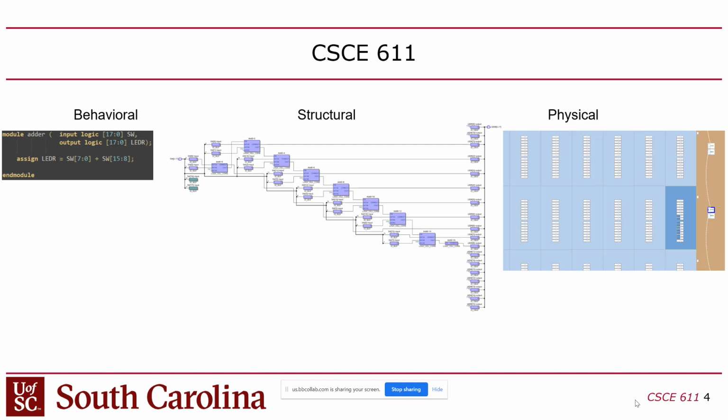So typically, most of the code you write is going to be a textual description of this kind of design. Instead of drawing a schematic, you're going to be writing it in code, and then sometimes you'll write some behavioral code, and it gets mixed in together. But there's basically two styles of SystemVerilog: structural and behavioral.